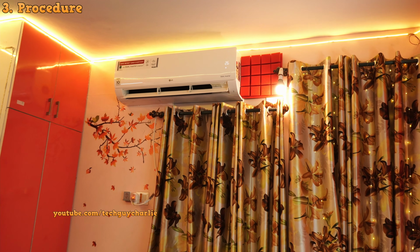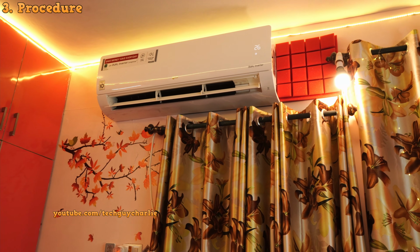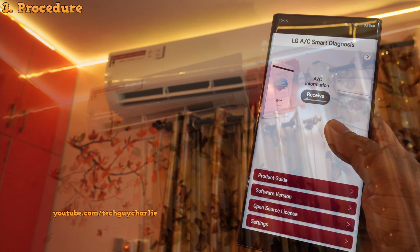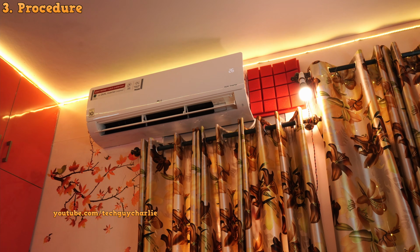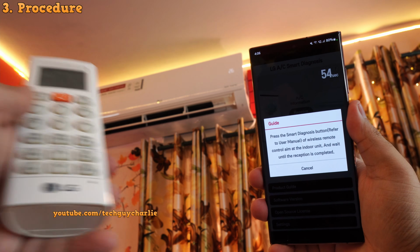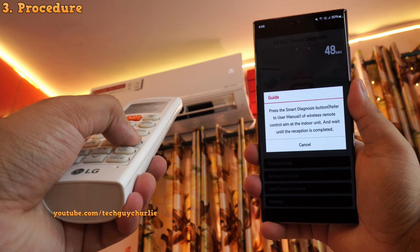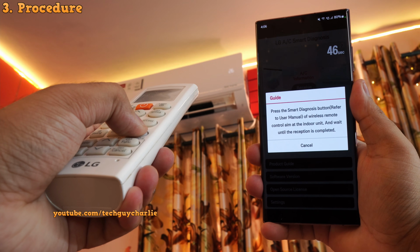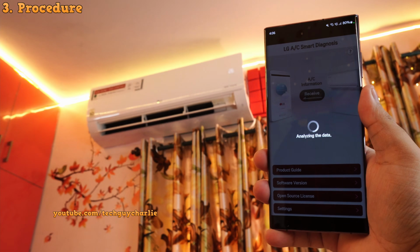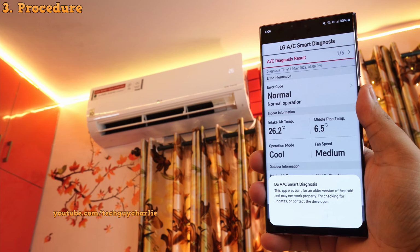Now before you begin, you must stand near the air conditioner, and secondly, you must make sure that there is no ambient noise because the air conditioner uses sound to communicate with the app. So once everything is nice and quiet in your room, press the receive button in the Smart Diagnosis app. Then grab the remote and press and hold the button which says diagnosis for 5 seconds until the air conditioner starts beeping like this. So now it is transferring information to the smartphone. And once it is done, you will see some useful information on your smartphone. Let me try and explain what all of this actually means.